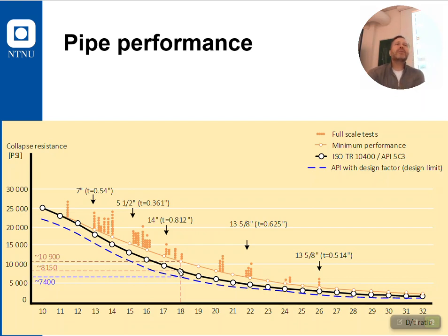So it means that any pipe manufactured should tolerate this with this D/t value of 18, it should endure this collapse stress, right? So you design so that the maximum collapse stress that this pipe is enduring doesn't exceed this blue line. That's how you do it.